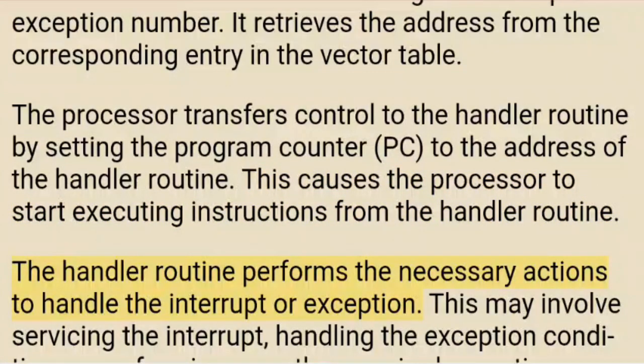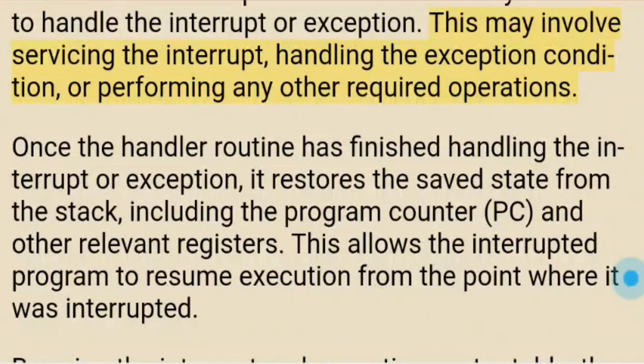The handler routine performs the necessary actions to handle the interrupt or exception. This may involve servicing the interrupt, handling the exception condition, or performing any other required operations. Once the handler routine has finished handling the interrupt or exception, it restores the saved state from the stack, including the program counter (PC) and other relevant registers. This allows the interrupted program to resume execution from the point where it was interrupted.